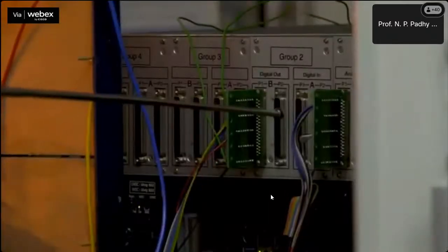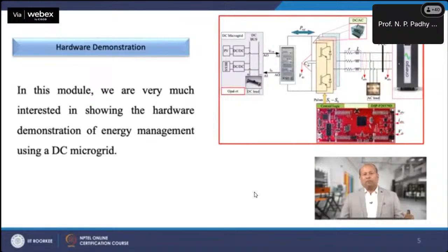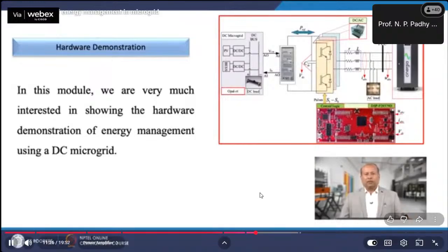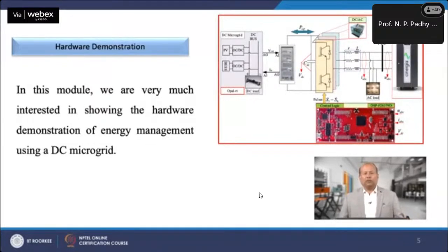To emulate the DC bus voltage through the power amplifier, the DC bus voltage is sent out through the analog out of Opal RT by scaling down to a 0 to 10 level, which is the power amplifier analog input voltage level. The power amplifier is configured to external mode, which gives the voltage corresponding to the analog input voltage value.